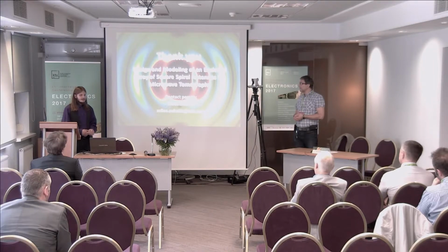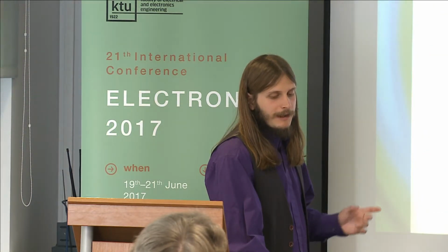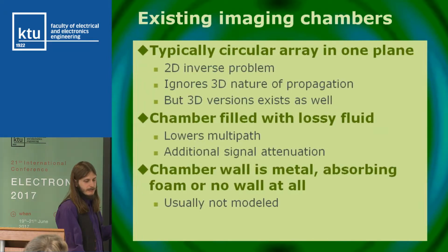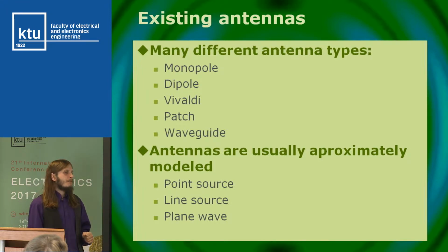Well, I think that we considered some certain antennas. Maybe the Vivaldi antenna is a typical one used in these applications. But Vivaldi antennas have curves which are not so easy to model in FDTD again, and we considered an approximated Vivaldi-like antenna made more square.